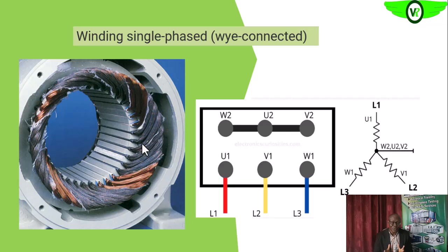So at times too, if you have a contactor on the line and the three poles are not closing at the same time, maybe 2 is closing before 1, before the 3rd one closes, it may have single phased for some time, and if that is repeated over time, it can result in this kind of thing.